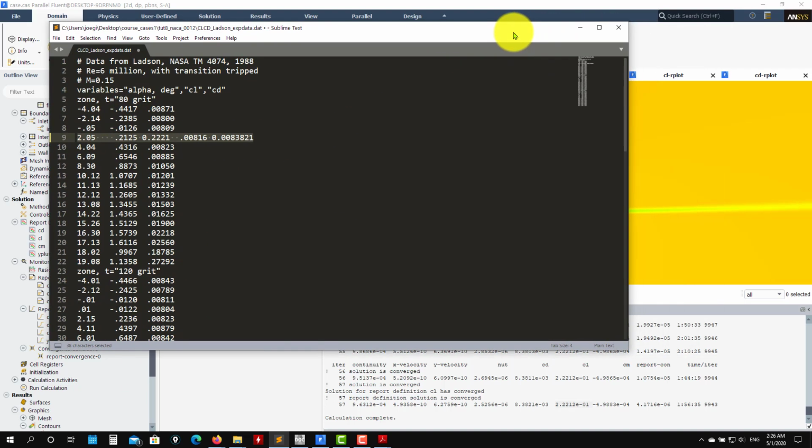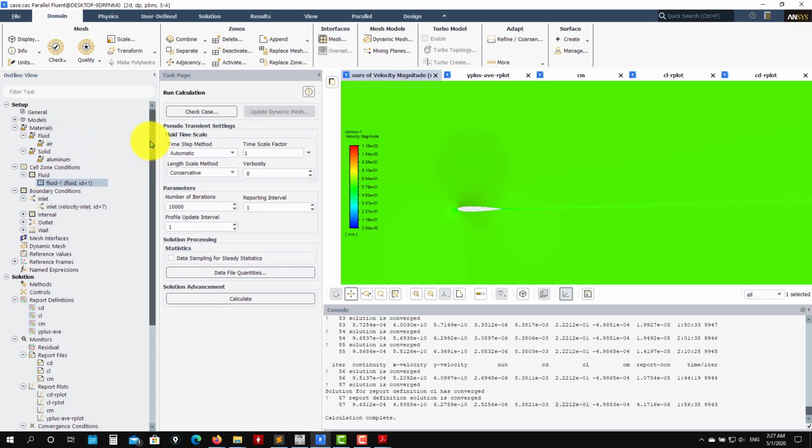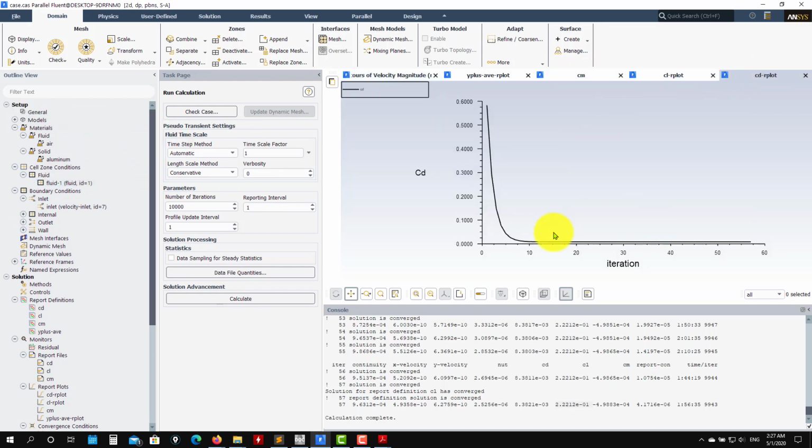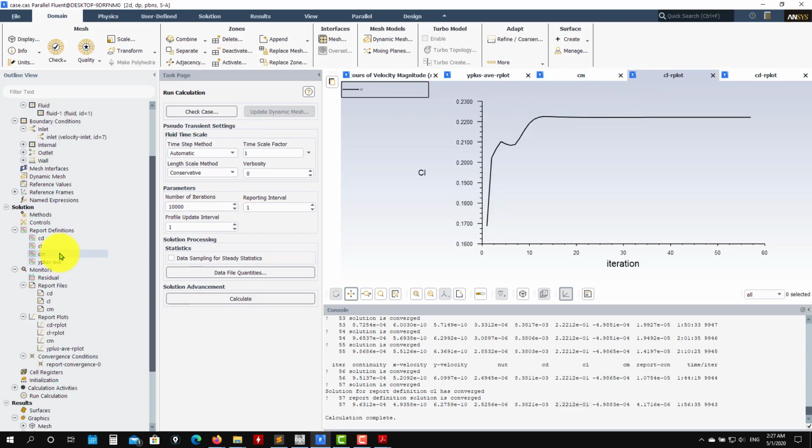The turbulence model will add that quantity that will stabilize everything. And why do I use that word stabilize? Because now let's rerun and let's switch off the turbulence model. So imprint in your mind, in your brain, in your eyes, this behavior, okay? See that it is very flat. So let's rerun, but now to rerun, let me initialize.